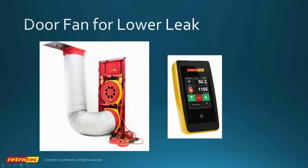This model of fan here, for those of you that go way back to our 900 fans that had a 20-inch duct, this is a 24-inch duct. The fans that we're using here are the 2 horsepower fans. They will blow a massive amount of air through this flex duct. This is a variable frequency drive that we have down here, which does a magnificent job of pressurizing above ceiling space. We also can have a number of flex ducts going to the above ceiling space.